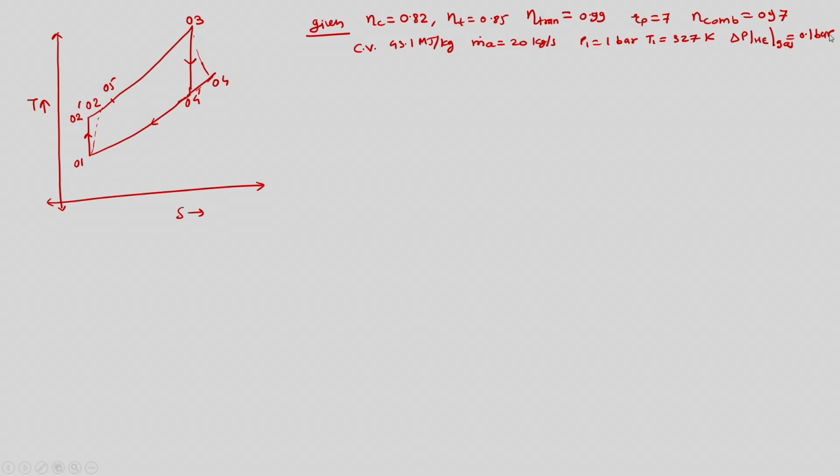So, practically the given fact is that P04 is not the same as P01, and so they are at different pressures. So, we will not connect them, or rather if at all we can connect them, we have to keep some gap, and that gap would be related to the pressure loss. So, we will solve with regenerator first, and then we can work out without regenerator.